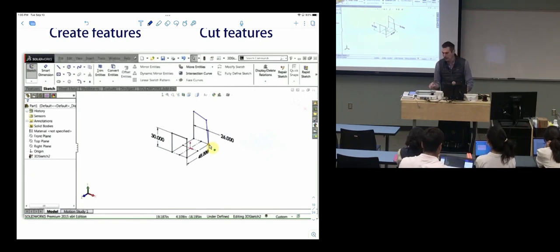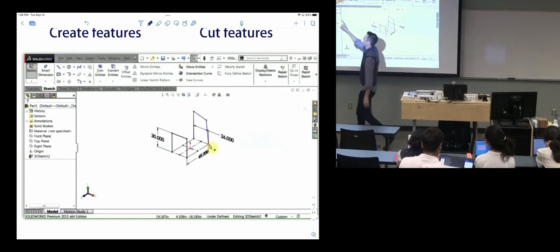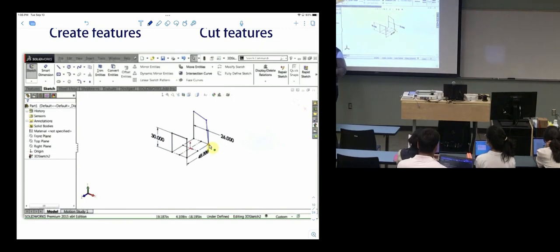If you click Exit Sketch, this button, it's kind of depressed. I press that, and it backs me out into the 3D shape that I'm trying to create, and asks me how deep I want this extrusion, for example. So if you do a 3D operation, the first thing it asks you to do is select a plane and draw a sketch. When you're done with the sketch, you hit Exit, and it brings you back out and prompts you, for example, how deep does it go, or if you're revolving it, how far does it revolve. So you'll build features this way, and you'll have to get the hang of it by messing with it, by actually doing it.